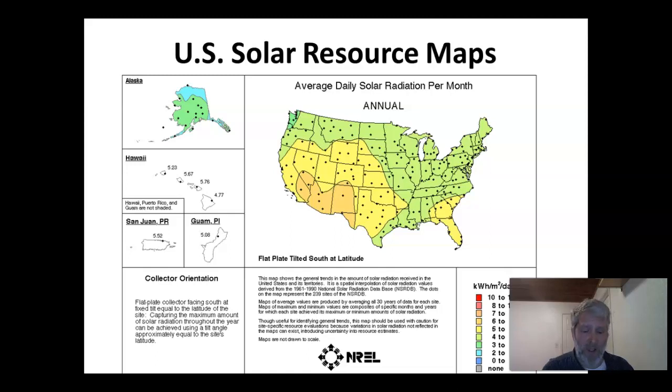So what that means is that you have to choose the worst day of the year, or at least if you have a couple of days where it's not going to work, then that's okay. But it's probably better to budget for those 0.9 suns versus the 2 suns, but at least budget for the 2 suns for building your battery bank, and then you'll be able to float that.